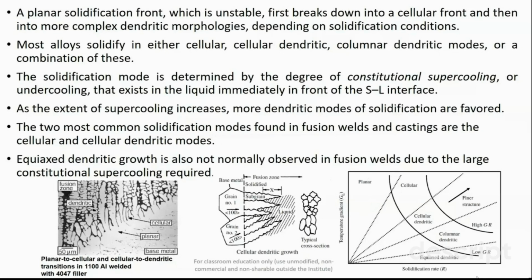Equiaxed dendritic growth is not normally observed in fusion weld due to the large constitutional supercooling required during the solidification stage. These are the points which I have discussed in the solidification of our weld metal.